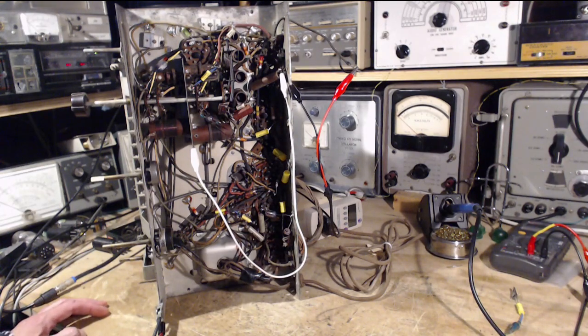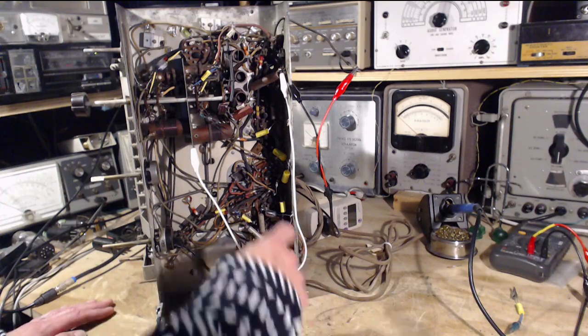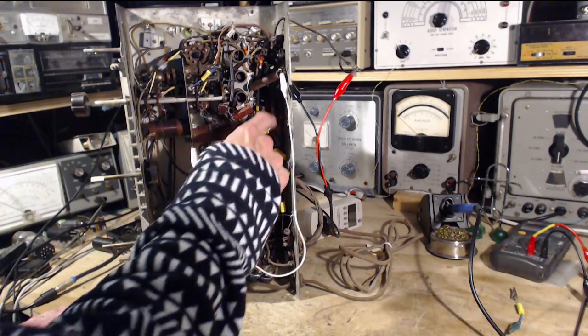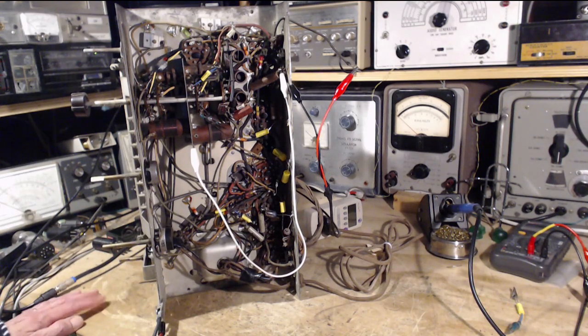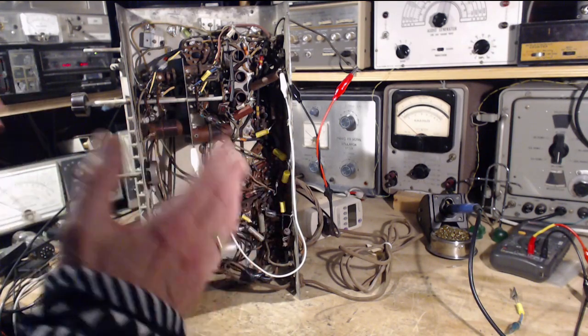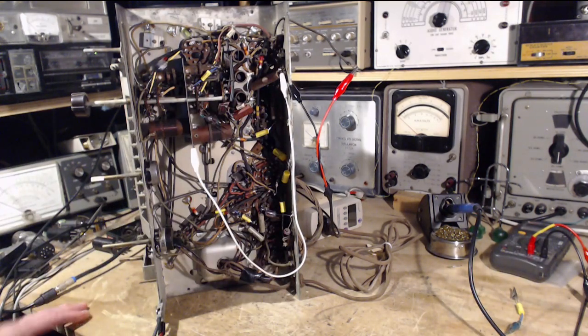Great. And I think now might be a good time to check some of these high wattage resistors. There's one sticking out right here. There's another one in here. Just take a quick look with an ohm meter and see if that test alone suggests there's a problem with those big wattage resistors. The next thing then is to fire up the radio and operate it after this has been changed, and take an inventory of its operation. Run through the bands, give it some signals from the signal generator, and just find out if all the bands are functioning and what's going on with this radio. Basically, that's the idea. That might be the end of today, or the next step after that is to go through the alignment of the radio.